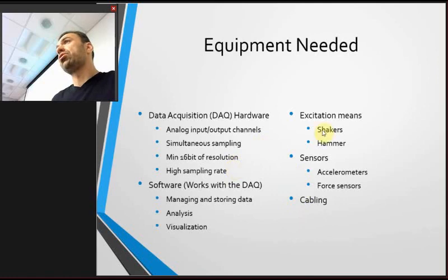The software needs to work with the hardware, and it acquires the data, controls the shakers, and also manages the whole test, the whole generated data from the test. And there is a lot of data coming from this test. We need something to excite the structure with shakers or hammers. We need to record the responses with accelerometers, and we need force sensors to record the input forces, and of course we need cables to connect all of it.